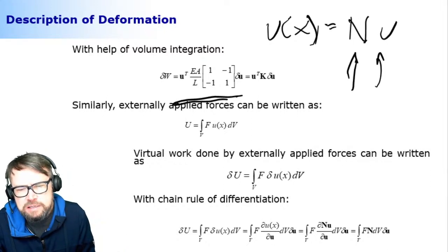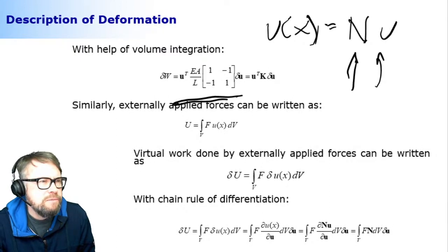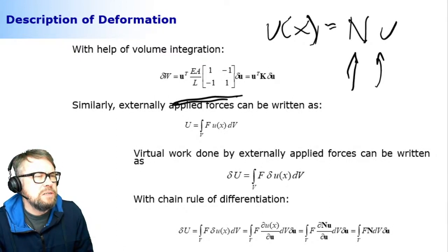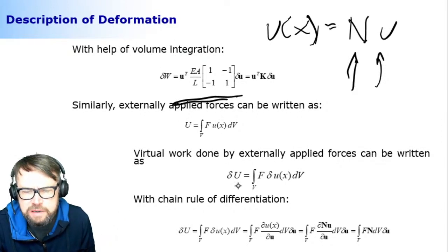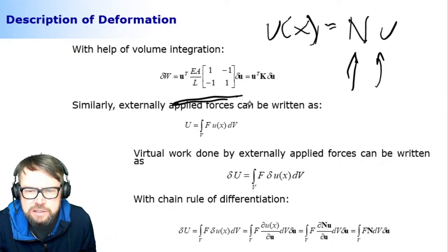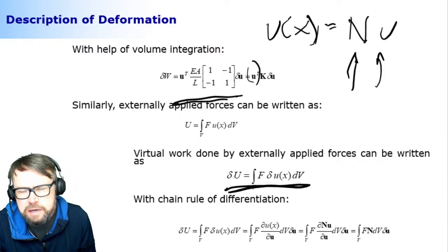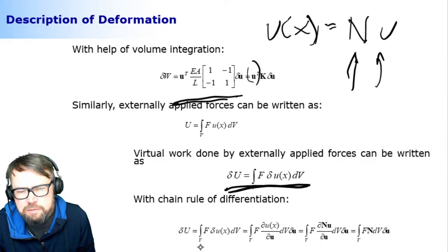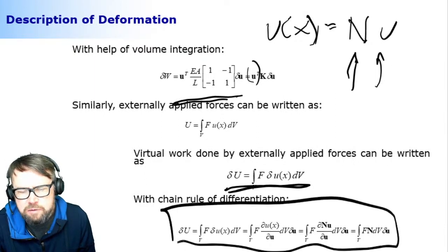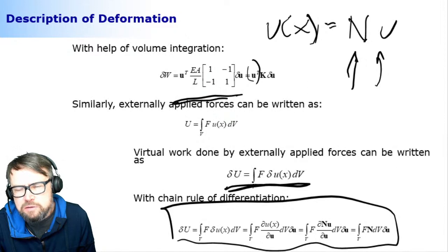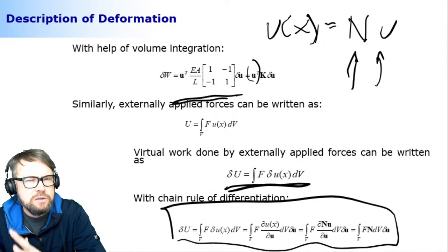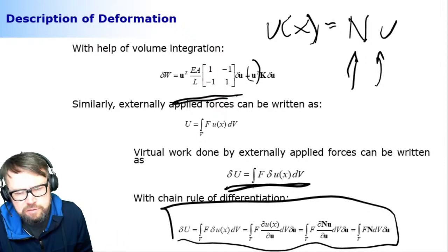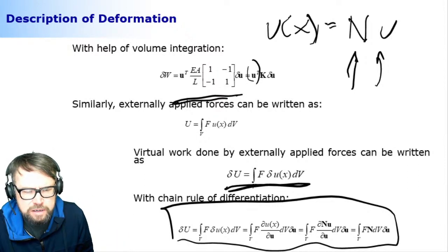One more thing about these finite element models is that, of course, forces too need to be expressed in terms of unknowns. And unknowns in finite element modeling are these nodal degrees of freedom. And you can do that too by using a shape function matrix. So you're following this idea. I'm not going to look at that in detail, but you can use the shape functions to express the forces that are imposed anywhere in the structure in terms of nodal degrees of freedom.